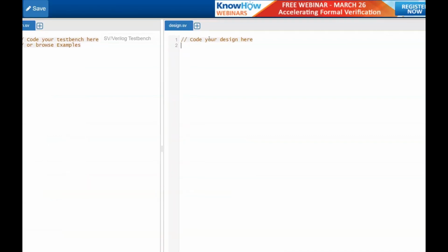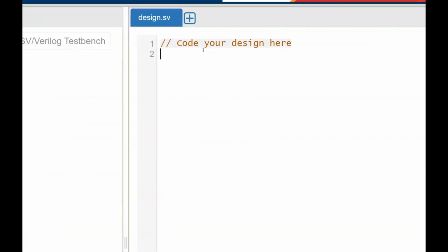Okay guys, now we will start making the Verilog code for the JK flip-flop. So nothing but a module. I am defining the module name as JK flip. And here what we require: inputs, I am taking reset, clock, J and K, and the outputs require output register, because it has to remember the previous state, so that based on the inputs it will change to the next state. So the outputs are Q and Q bar, and I am closing this.